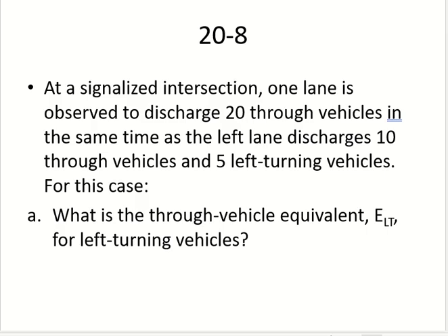Now let us look at one example which shows how these factors are calculated. They are calculated on the basis of time. We said critical is the one which needs more time, right? So the equivalency factor also depends upon time. Compared to a through vehicle, a left turning will need how much more time? That is the equivalency factor. So how do we do that?